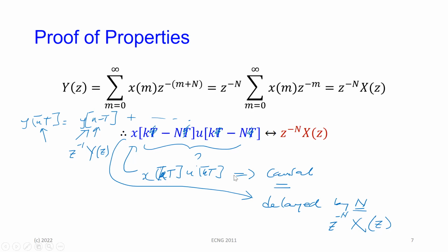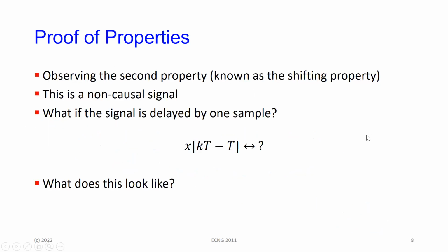The other version now is, what if we are not dealing with our causal signal? Because, as we said, discrete time signals, a lot of them you can store. So like music signals or the counter. The 3-bit counter, for instance, starts 000, 001, 010, 011, then 100, etc., and it goes all the way up to 111, and then presumably could start back over.